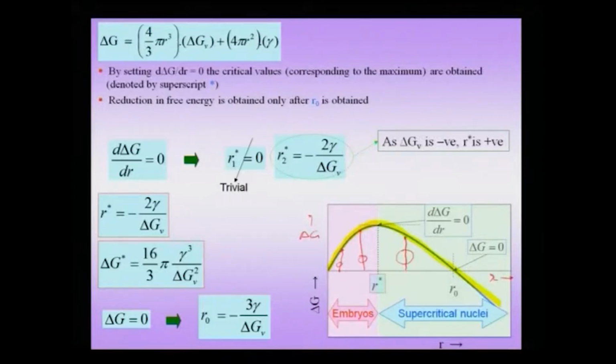then I notice that there is a reduction, it is similar to this. And finally, of course, beyond a value r 0, if I grow a very large precipitate like this, a very large solid, then actually there is a reduction in the free energy. That means, if I have a liquid and a small r forms, the energy of the system does not decrease, but actually increases. So, even though we are below the bulk freezing point, or the bulk melting point to be more precise, the system does not benefit if this small volume becomes a solid; the energy of the system actually increases.